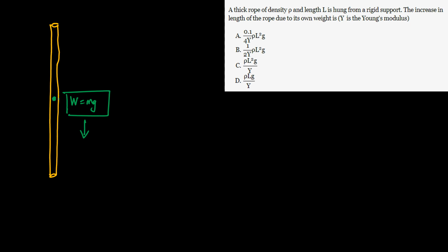Now what you gotta do? You gotta plug in the value of Y. You see Y over here, Young's modulus is given. Y is the Young's modulus. So first I will write down what is the Young's modulus. I know that the Young's modulus is the ratio of stress over strain. And what is your stress? Sigma is F divided by A. You can write this as big A, because small a is your acceleration. And here the strain is your delta L divided by L. And now this can be written down as F multiplied by L divided by A multiplied by delta L.